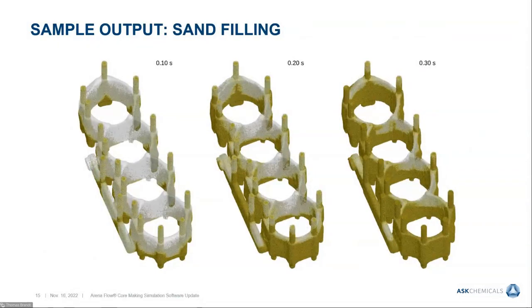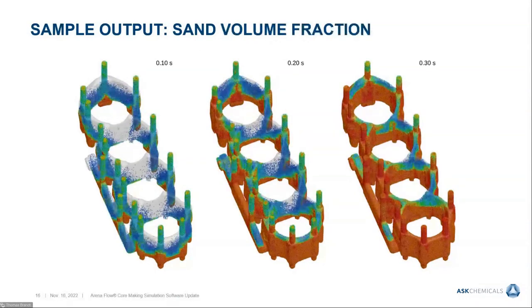Turning the tool transparent, looking at particles as they fill the cavity. Particle volume fraction, so sand to air ratio, again in the cavity, various time steps. Orange being compacted sand, blue being loosely compacted and still moving. Again, it's clear to see that the areas between the blow tubes in the right side image are filling slowly and could be potential problem areas.